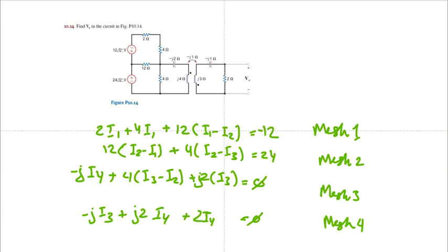Hello, in this video of the electrical engineering series we're going to be exploring magnetically coupled networks of two inductors. As you can see, we have a bunch of meshes on the left side, and two magnetically coupled inductors with minus 1 ohms, or J, because in electrical engineering we use J instead of I as the imaginary number, so we don't get confused between current and the imaginary number I. And the goal of this exercise is to find the voltage at the 2 ohm resistor